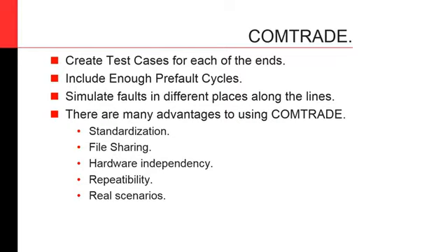And the other thing that it allows is not just to see, but to be played back using modern relay test sets. Since ComTrade is standard, it also allows hardware independence in terms of testing. As long as your relay test set has the ability to play back those files, you can use any relay test set to play them back. Say there was a fault in the system and the fault got recorded in a relay or some sort of recorder.